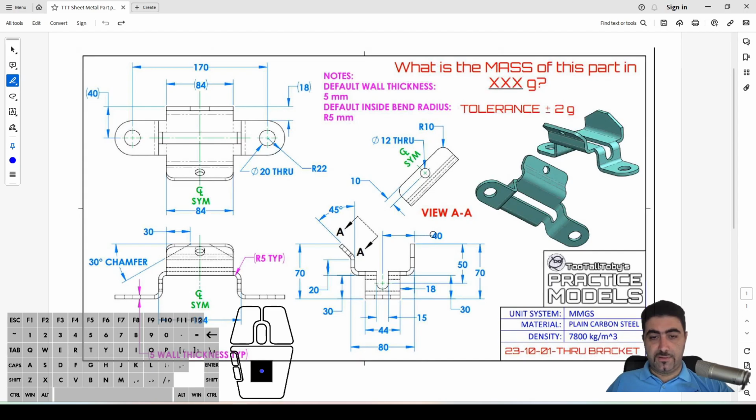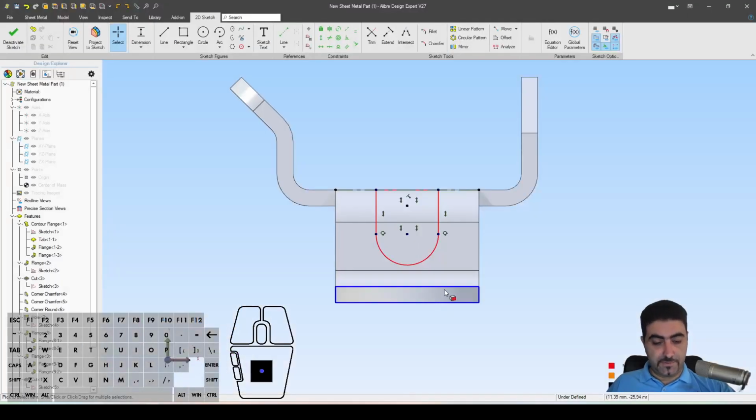So this is in the middle. Yeah, that 40 value, we don't need it. We just located with the origin. We do need to know the radius or diameter of this arc, and we get a value here saying that the diameter of this thing is 15 millimeters. So I click. Because it's not a full circle, Alibre is going to give me the arc. But if I hold shift and move my mouse slightly, I now get the diameter.